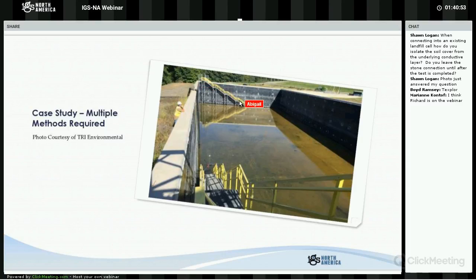These structures, these ladders that you see here, the first time I saw this tank, I said, no way. And they said, don't worry, they're fiberglass stairways. They're actually fiberglass, so you can perform a dipole method survey of the bottom, and this will not conduct electricity out of the cell. So this particular tank, you could do water dipole on the bottom, detect leaks through the concrete, and arc testing on the sides, on the walls there. Those are the two perfect methods for these conditions.